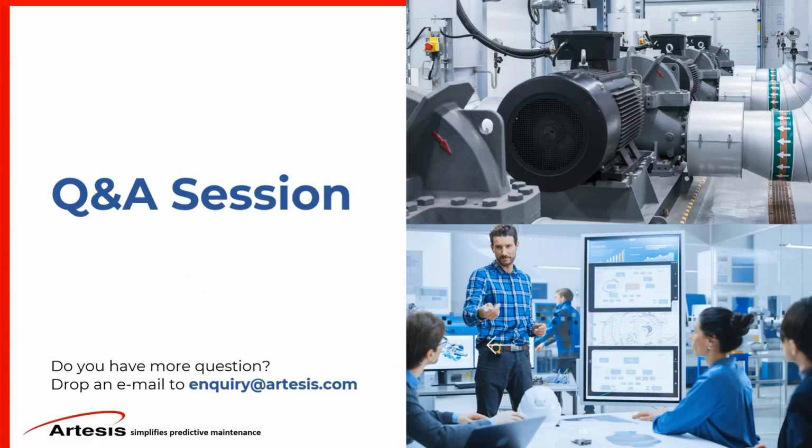How to separate normal and caution signals in spectral density? This is a question for another time, but we have done a lot of webinars on this. It's a very lengthy explanation, so I don't want to get into that. Does vibration analysis include RMS only or orbital analysis? We're not doing orbital analysis. We're not using RMS. We're taking the raw waveforms sampled at 10 kilohertz.